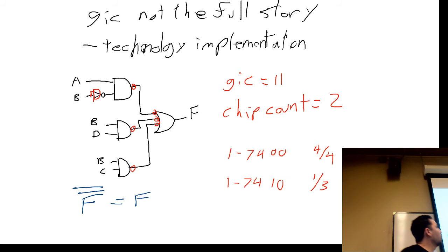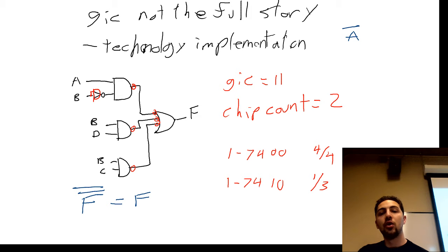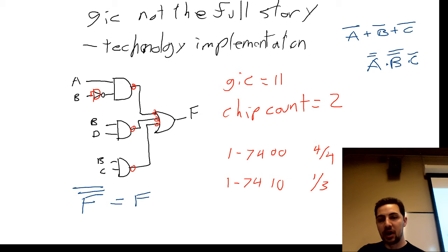No, an OR with all of its inputs inverted, bubble push this. No, it becomes a NAND. It becomes a NAND because if you've got A bar ORed with B bar ORed with C bar, that becomes A and B and C double bar with an inverter all the way over it.